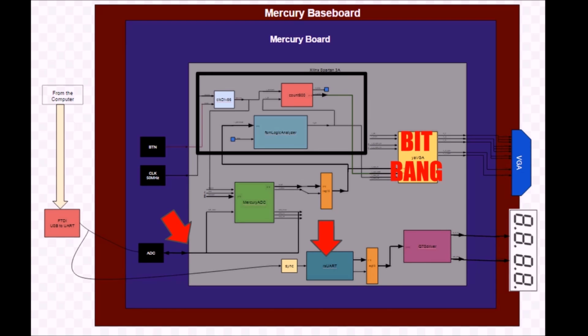But if you bit bang, your software is pretty much locked up setting its timers so it knows when to set the pixels at the right time and when to activate the horizontal sync and vertical sync lines. Because your software can only do one thing at one time, you can pretty much forget about driving a quad 7-segment display. You'll have to get an external driver chip to drive these segments for you. Then you'll have to implement this logic, which should be doable but would be a pain.